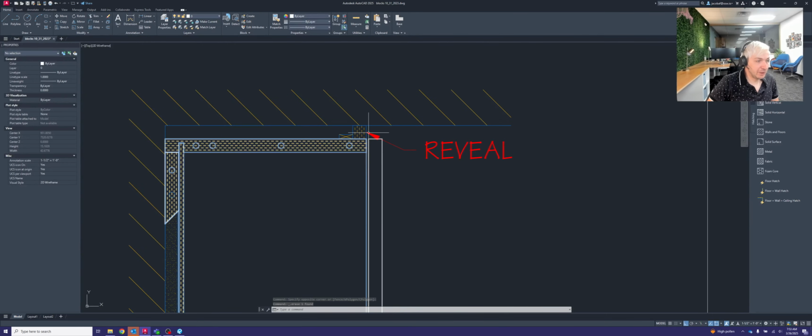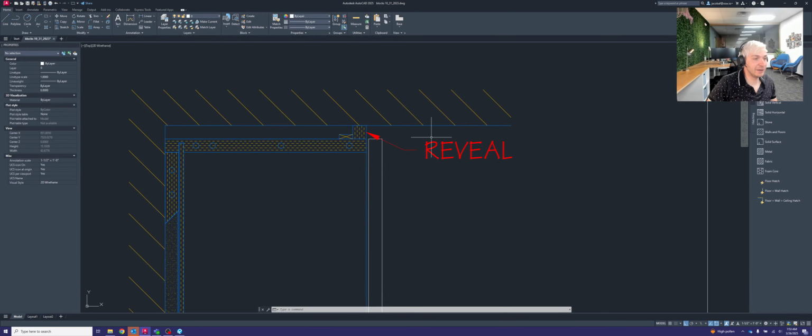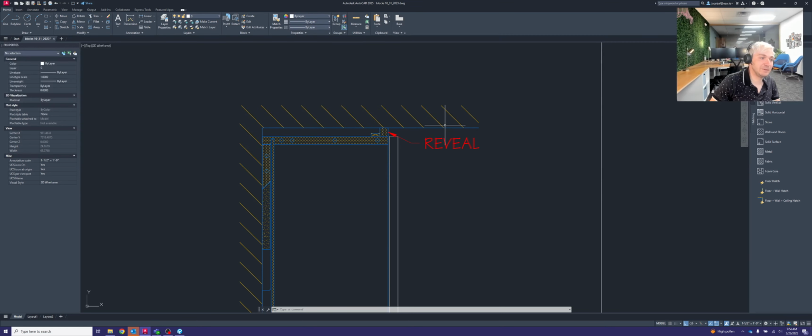Again, that's usually going to be 3/4 of an inch tall, and that'll go above your upper cabinet if you have a ceiling above your cabinet. If you don't have a ceiling above your cabinet, you don't even have to worry about that reveal. That's completely unnecessary when you don't have a ceiling above your cabinet. But if you do, be really careful. You're going to want to add that in. A lot of times architects will not show that because they don't really have a full understanding of how a cabinet is installed. So we have to remember to add that in on our own. Just a real important note there.